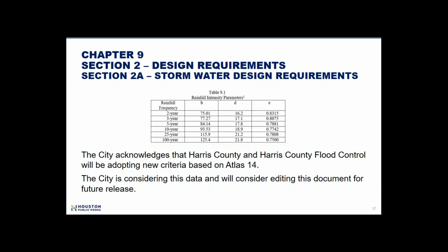However, we are intending to move forward as soon as possible with pretty much a study of our own to look at the Atlas 14 data as it applies to urbanized areas, highly urbanized areas like the city of Houston. Harris County's criteria might very well cover urban areas, but the majority of what they deal with is rural or suburban, not as densely populated as we deal with, not having to deal with entire huge areas of storm sewers versus open channels. So we are going to be looking at that ourselves.